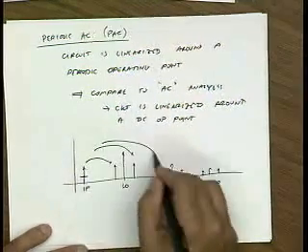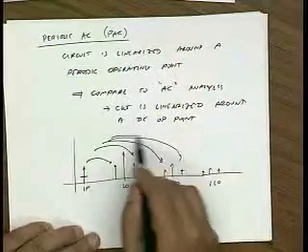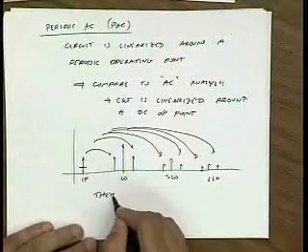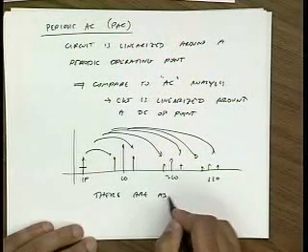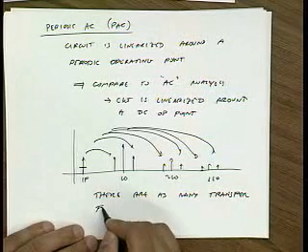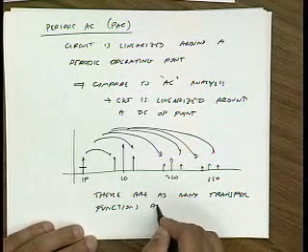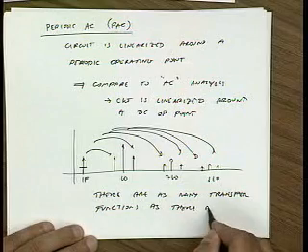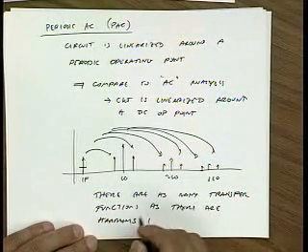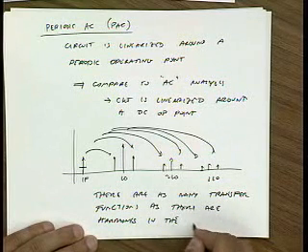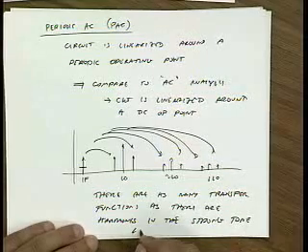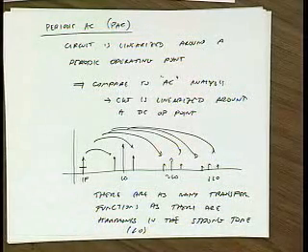So which transfer function should we look at? And how many transfer functions are there? There are as many transfer functions as there are harmonics in the strong tone. That might be the LO in the case of a mixer.